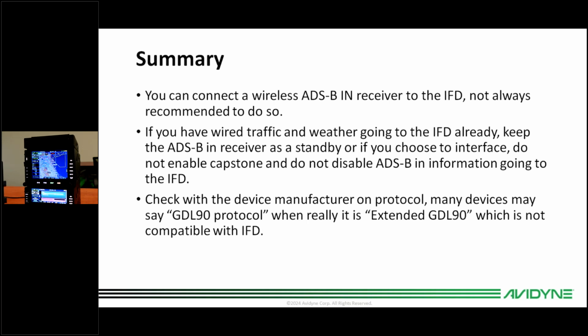Or if you choose to interface these three things together, even if you are receiving traffic and weather, do not enable Capstone in the IFD in maintenance mode, and do not disable the ADS-B in information going to the IFD. Those will keep all the devices happy, and you won't have any configuration problems. I do not recommend changing any configurations aside from that one Capstone enabled protocol. And again, check with your device manufacturer on the protocol. Many devices advertise that they use GDL90 protocol, when really it's actually extended GDL90, which is not compatible with the IFD.